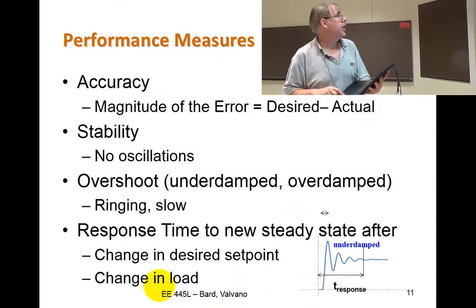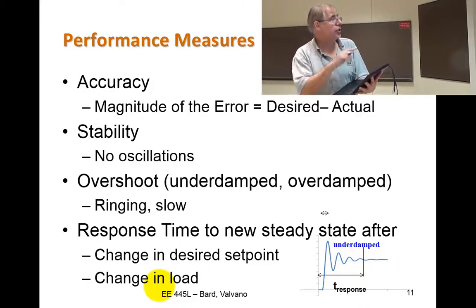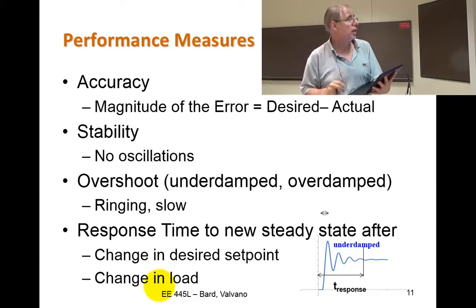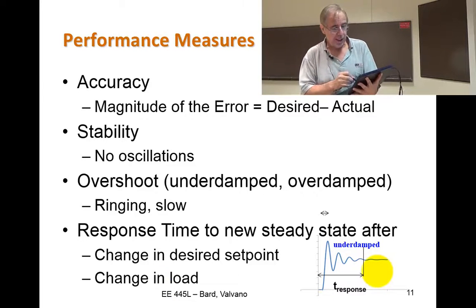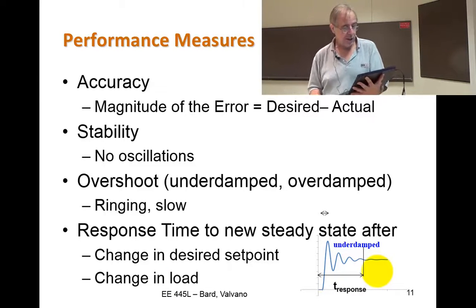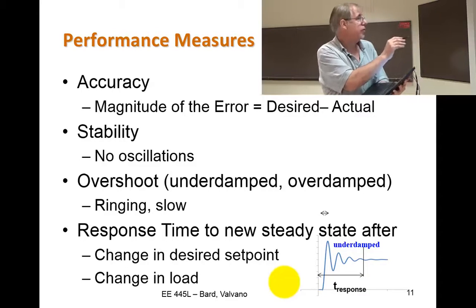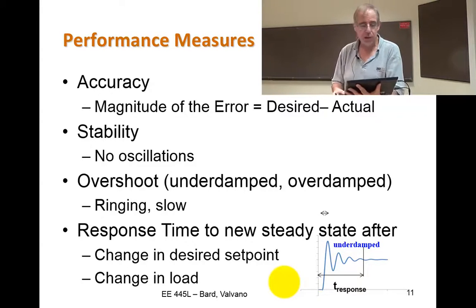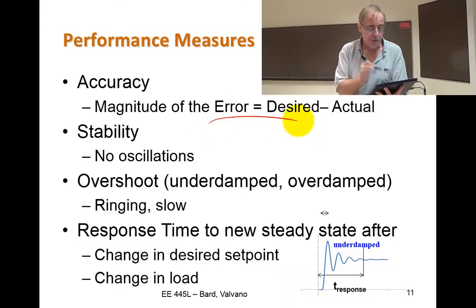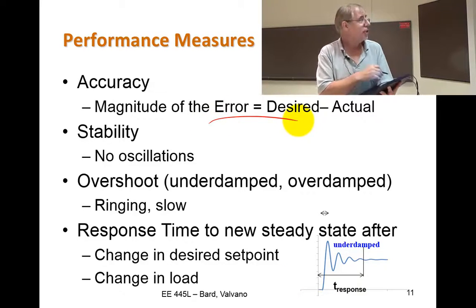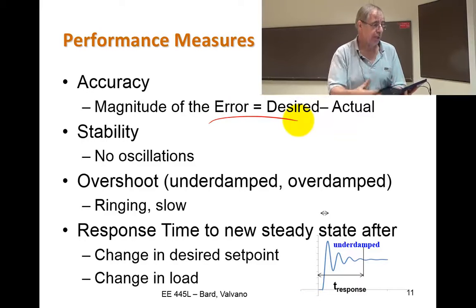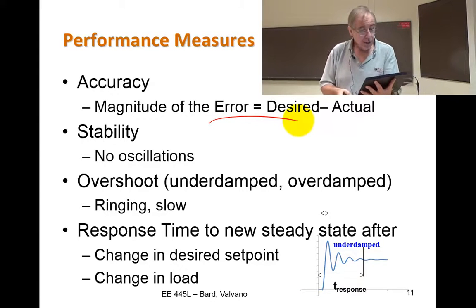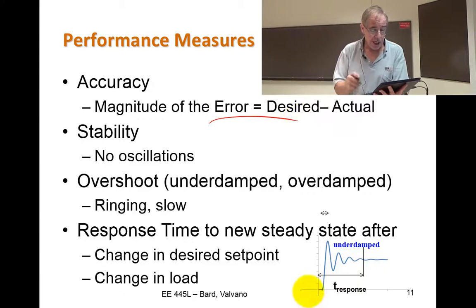We'll see accuracy, stability. Overshoot's interesting. You're going to see overshoot, and that is once I set my set point, it'll go too fast. And then we have transient response, and I'll show you these two in the demo. I don't care what they are, you should just know what the terms are. Accuracy is the difference between desired and actual. Stability means does it actually spin and doesn't blow itself up. And the response time, which has actually three phases.